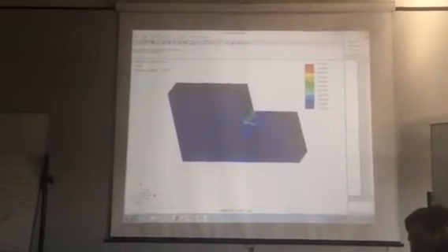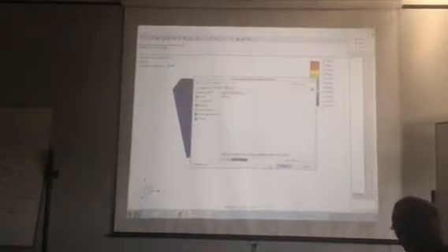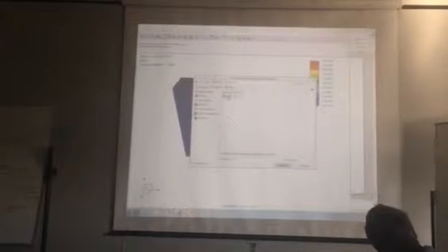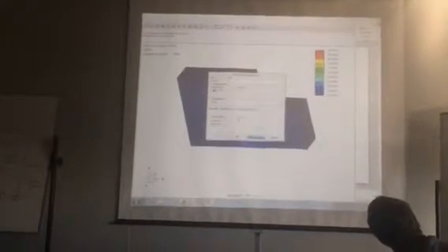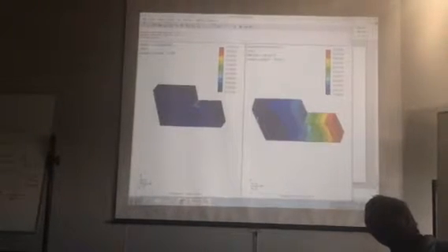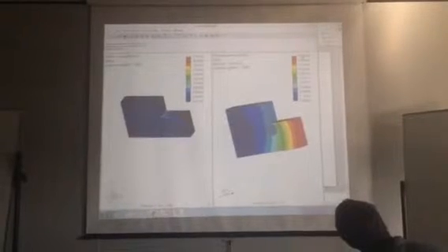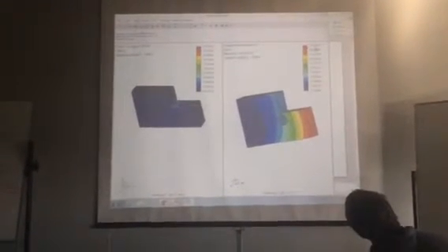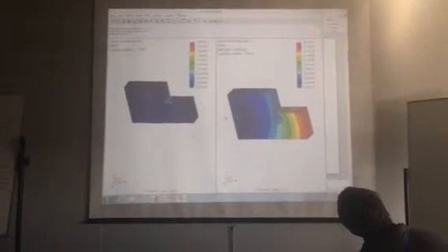So, in here we can go insert result window. So we're going to put a new window in. If we go here, we can go displacement in millimeters and OK show. So this is our displacement of the beam. We can see in millimeters that the red area is going 0.023. So it's very simple to use the Creo stuff.